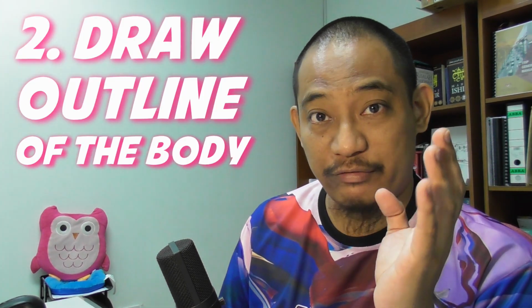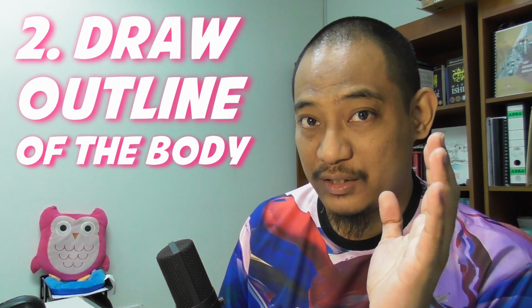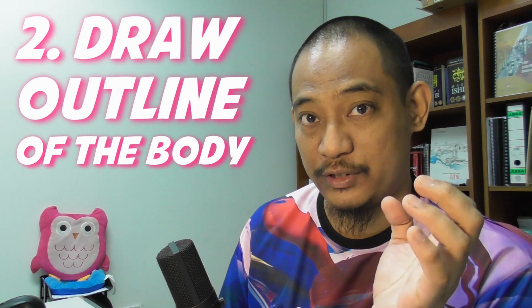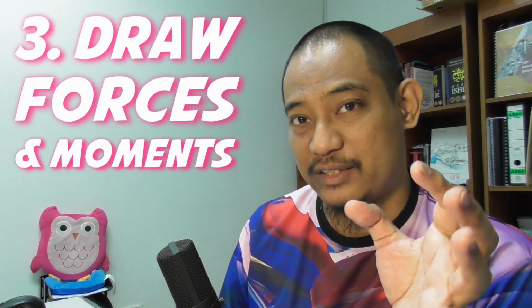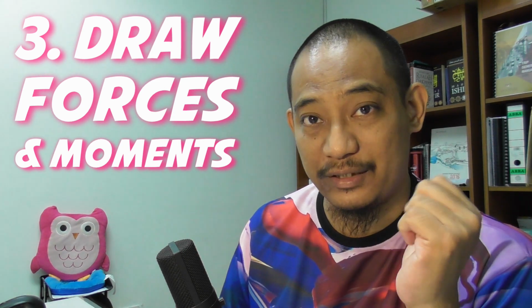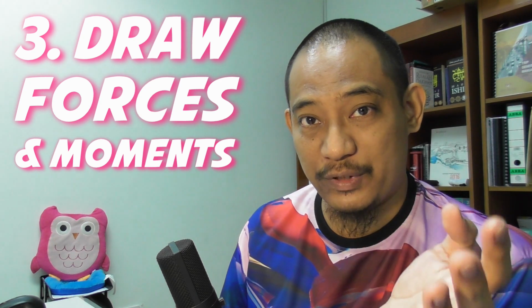We will cover some examples after this, but this is the first step, determining which body. Step number two, draw the outline of the body. This is straightforward. Number three, draw all the forces acting on that body. This may include the weight if the weight is given. Please take note that each force has its own value, the magnitude of the force, and the direction. So both pieces of information should be there in your free body diagram.